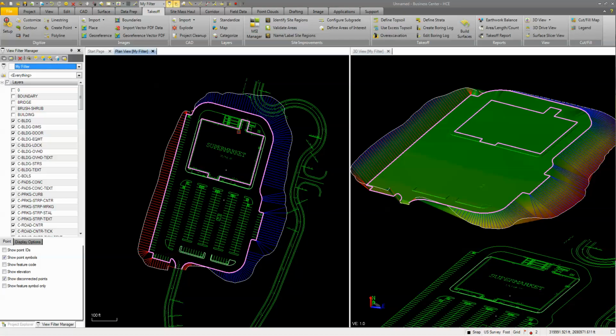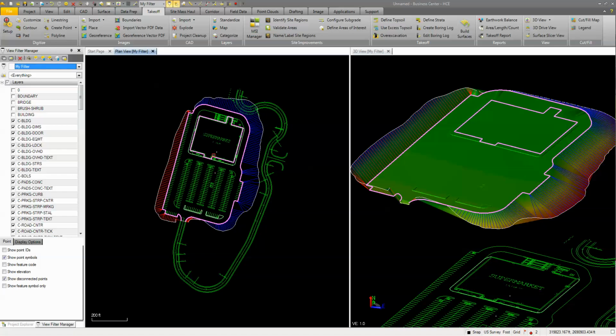But we know, again, this is rough. So if we set our finished floor elevation, instead of using 450, we use 455 moving forward, when we get into the detailed design, then that should somewhat balance out. We can adjust it again later once we start to get into more detail, but at least we have a good idea, with the preliminary grading, of what our finished floor should be and what we can do moving forward with the rest of the design.